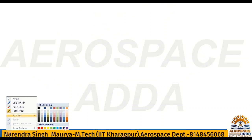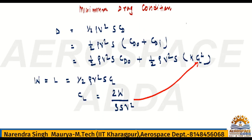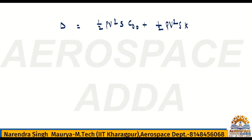So this drag is half rho V square S into CD naught plus half rho V square S into K CL square, where CL is 2W divided by rho S V square.